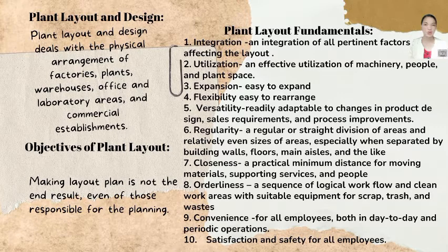These include, first, integration of all pertinent factors affecting the layout. Second, utilization, an effective utilization of machinery, people, and plant space. Third, expansion, easy to expand. Fourth, flexibility, easy to rearrange. Fifth, versatility, readily adaptable to changes in product design, sales requirements, and process improvements. Sixth, regulation, regular or straight division of areas, and relatively even sizes of areas.